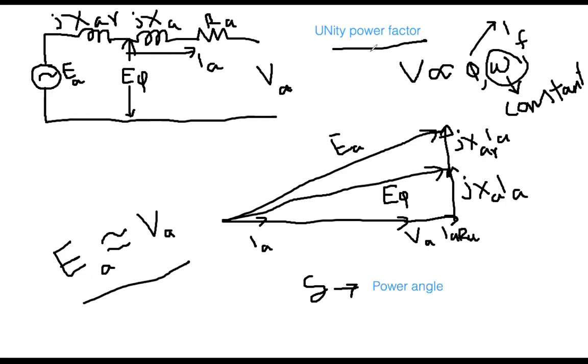So meaning that when the power factor is unity, customers are consuming mainly resistive load. In that case, your terminal voltage and internal generator voltage are almost close, a little bit bigger, but very close. Meaning that you don't need very high excitation, and you don't need very little excitation, a normal situation. Accordingly, the conclusion for the unity power factor case is that you need normal excitation.